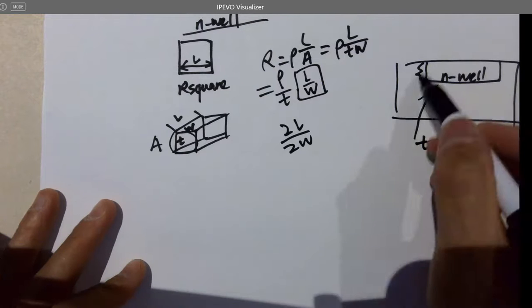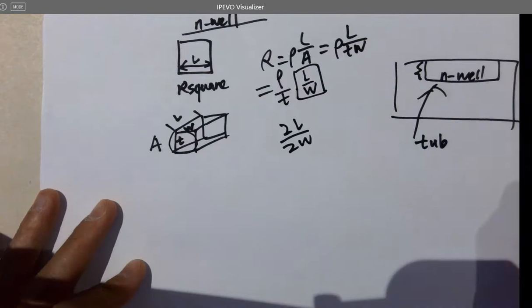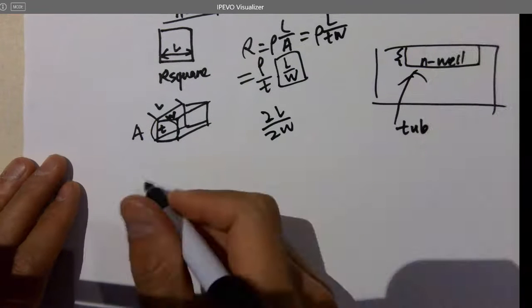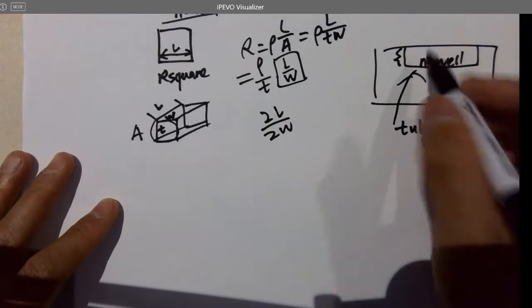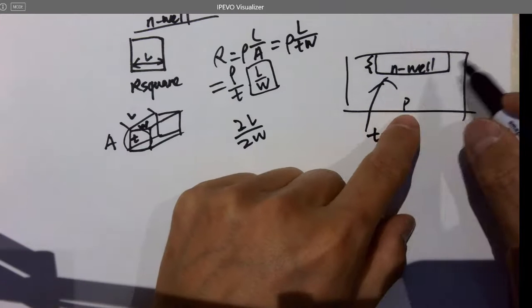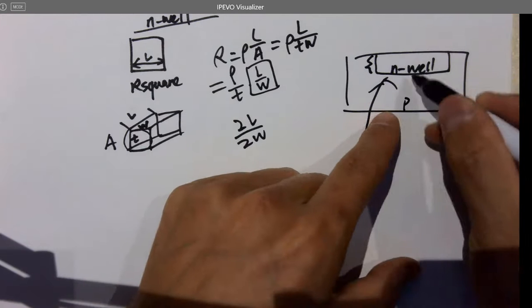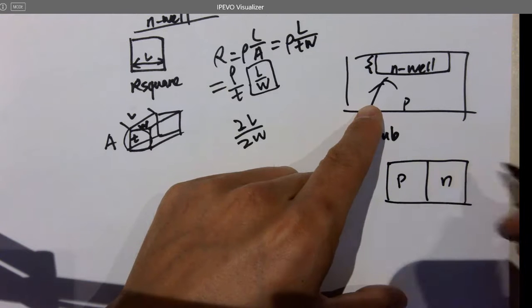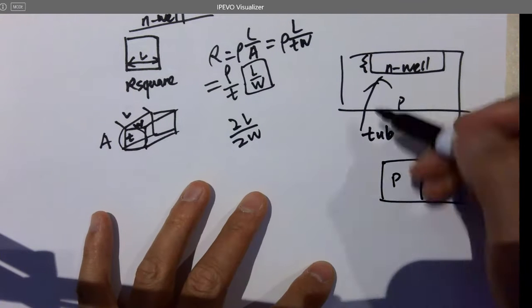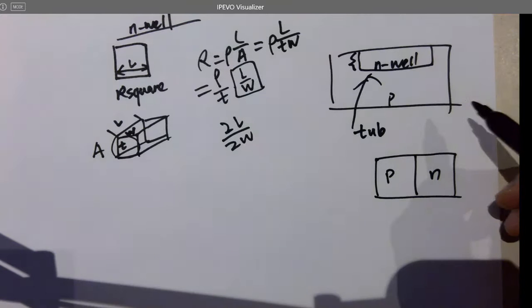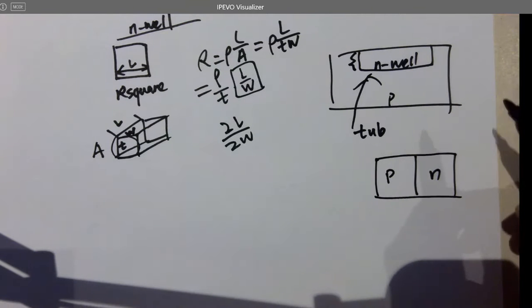And if you have an N well, it's a pretty long well, like a long wire, but it's a well, then it has a delay. The reason is the N well is an N material and this is a P material. Since we have learned semiconductors, we know that's a PN junction. What's going to happen for the PN junction? Whenever you put them together, what's going to be formed after a well?